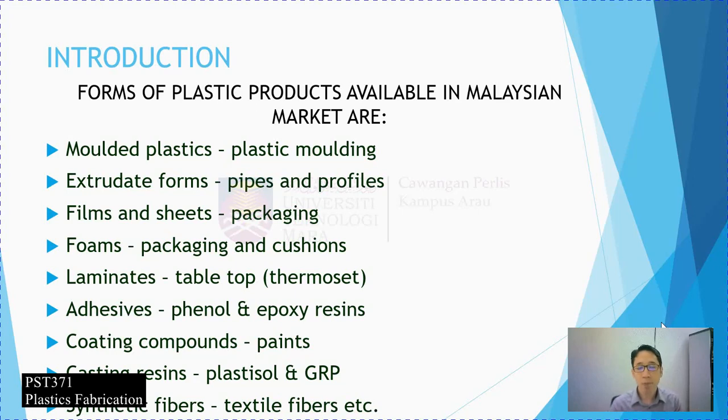For example, as we know, the surface of polymer material is hydrophobic. So with this limitation, it rarely adheres properly to the surface of metal, ceramic, other plastics, wood, fabric, etc. So adhesives enhance the capability of the coatings or paints to adhere